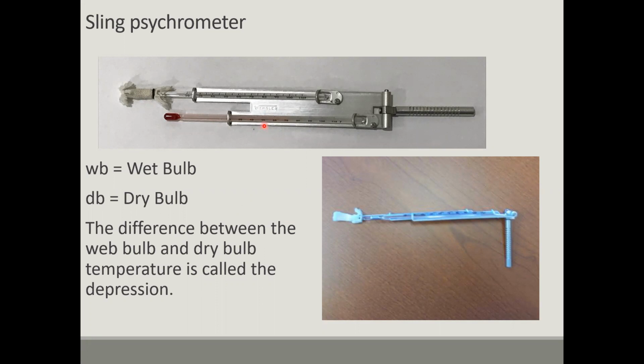Yes, just like the thermometer sitting on the wall. What's happening to this one though? Well, in your climate, it's very dry, is it not? Now the sock is drying out. The water is evaporating. When the water evaporates, it gets colder.